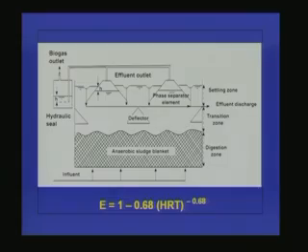For example, in Kanpur, initially they set up a 5 MLD treatment plant for domestic wastewater, and seeing that it was a success, they put up another treatment plant with a capacity of 36 MLD, which uses domestic sewage as well as wastewater from the tannery industries. So this is used for the treatment of municipal as well as industrial wastewaters.